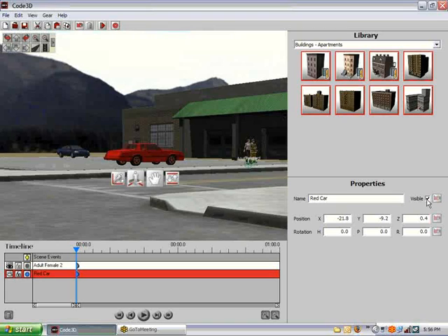If you find that you have recently changed a property of an object and you would prefer to undo that change, you can do this from the Properties panel. Each property listed in the Properties panel has its own reset feature. If you do not like a change that you have made, you will click the red Reset button that is directly to the right of the property you wish to reset. Once you click the button, the property will revert back to its previous value.